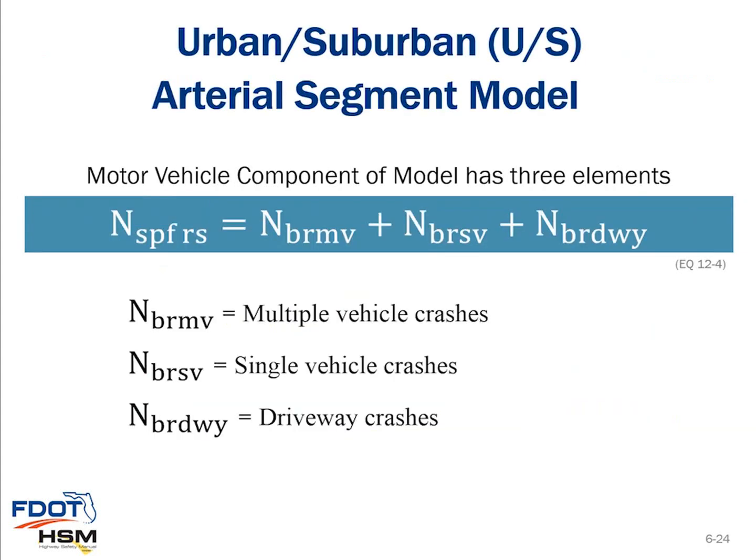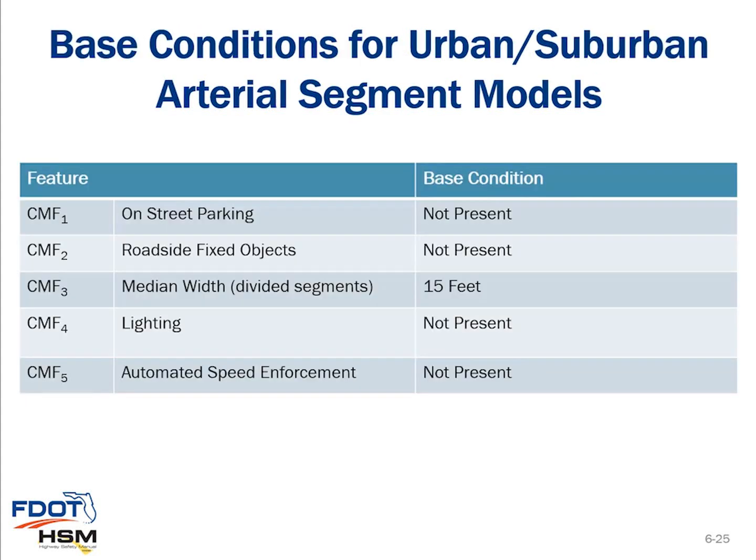As we look at the different components of this, we'll go through the analysis procedures for multiple vehicle crashes, single vehicle crashes, and driveway crashes. They all total up to become the overall motor vehicle component, and then you apply the crash modification factors to the sum of these three different crash types.